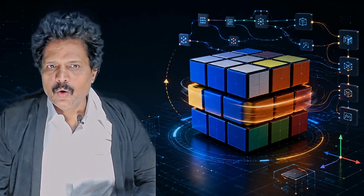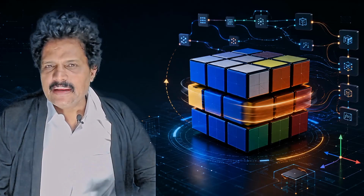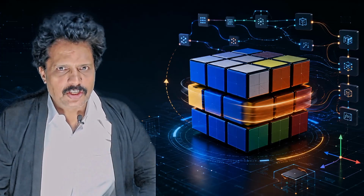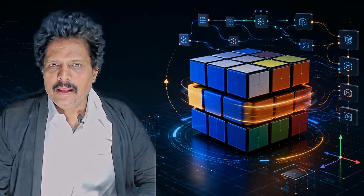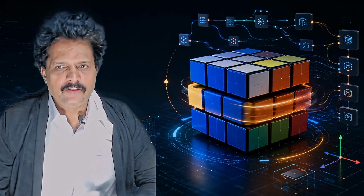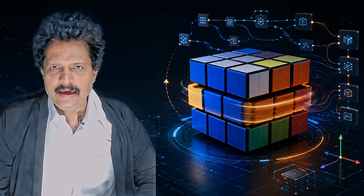We will learn how to store rotation values using named attributes, almost like variables in a programming language. We will create values such as a new rotation value, old rotation value and difference rotation. Then we will calculate how much the cube layer should rotate only when the input value changes. After that, we will use a map range node to convert simple input values into precise rotational values. This will help us rotate the Rubik cube layer accurately at 90-degree angles.